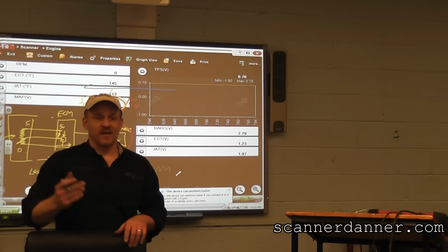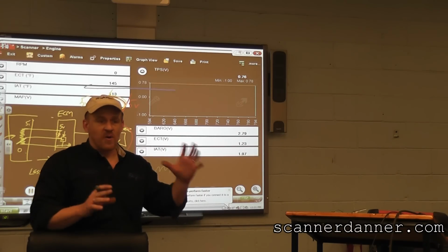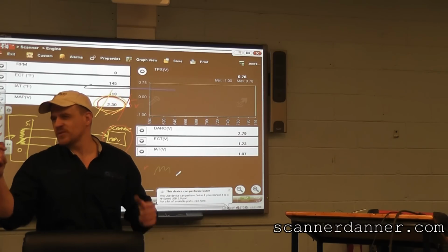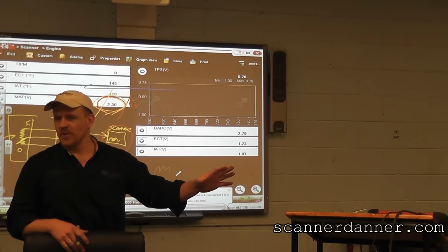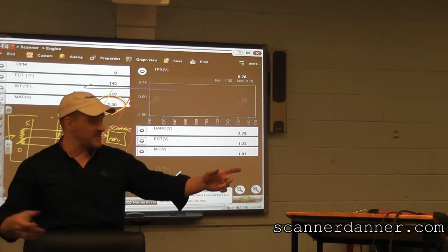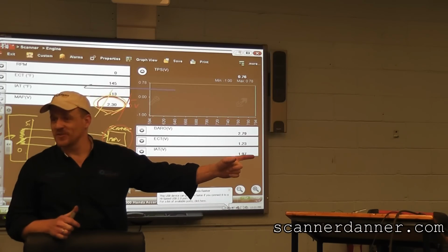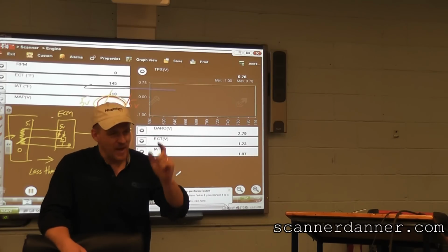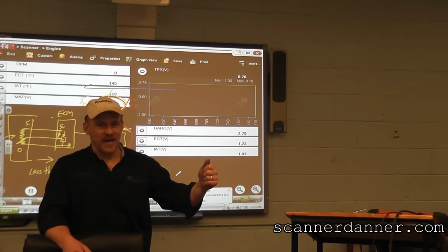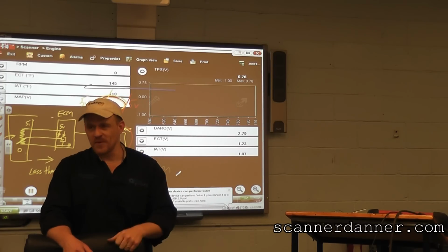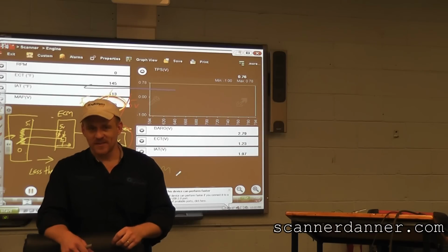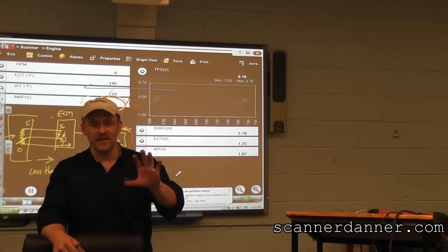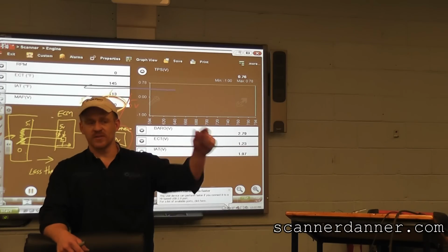Okay, so that was the test I wanted to show you guys, like the live part. Wasn't able to show you. If I can go to a sensor, if that sensor was actually faulty, causing the 2.3 volts all the time, which I assumed it wasn't, until I saw it was a new MAP sensor. It looks new. If that MAP was faulty, a simple unplug it test and that going to 5 would tell me what? That sensor has an internal resistor and also would tell me that my signal wire's fine, reference circuit is fine, most likely bad sensor.